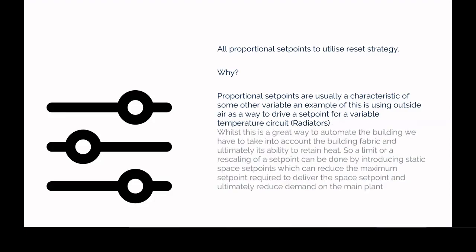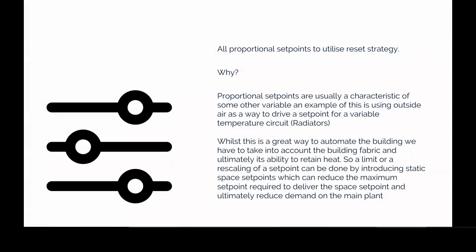Why is that important? Let's be honest, it's less demand on the boiler. Therefore, you can start to reduce your VT set point. Going back to what I was saying before, if you're reducing your VT set point because there's a lack of demand, and you're maintaining your fresh air or supply air from your main ventilation, then you can start to reduce your boiler set point, therefore reducing your gas.